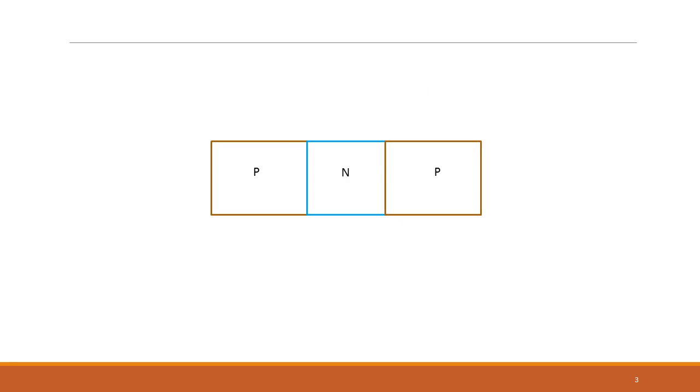So let's assume you have a PN junction, to which you strap on another PN junction. So there's a PN junction here and there's a PN junction here. Remember, the diode was just this PN junction and you had contacted it externally through this. So to the base, to the N type material, you add another PN junction here. And let's say you make the base width small. This N type region, small. We compress it for some particular reason, but let's assume that you have done that.